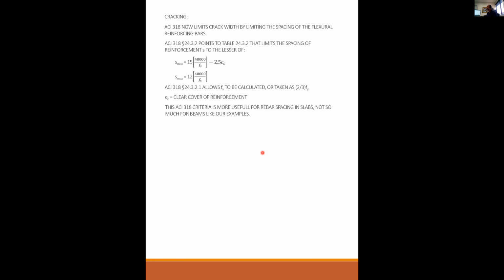And once you have decided the depth of the beam and the steel that you're going to use, both of those are going to give you numbers different than the minimum required. So D minimum and the D that you build are different things. AS minimum and the steel that you choose are different things.